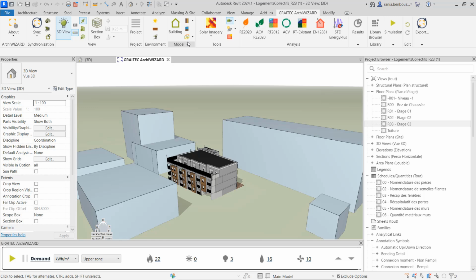Parameters help you configure the building information, such as zones, the scenarios, the wall composition, the glazed area composition, and the thermal bridges. Then there are some bioclimatic tools that we are going to use, such as the solar imagery, and all the previously presented modules, including the DTS module for detailed simulation.